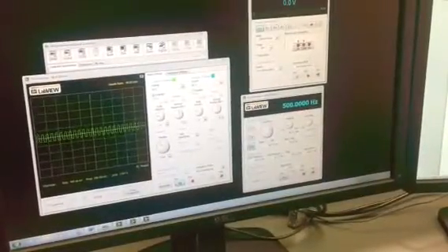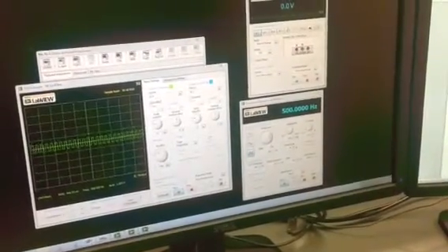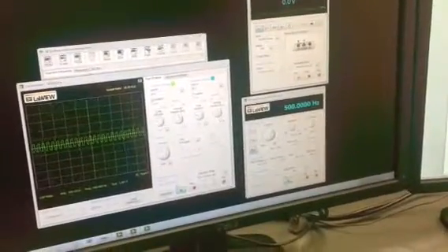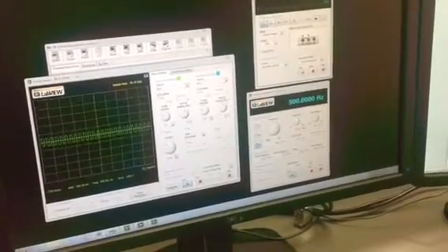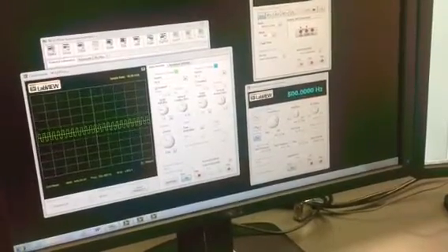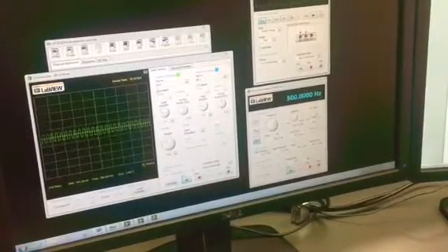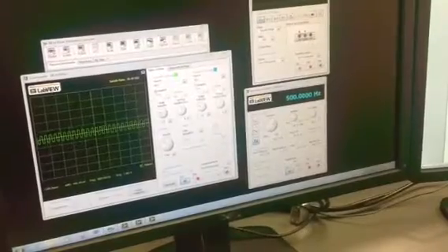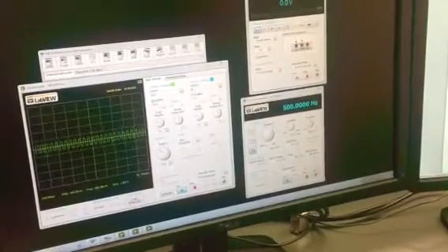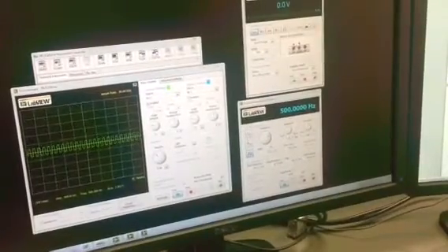For part 8, use a square wave of amplitude 2 volts peak-to-peak as the input voltage into the RC circuit. With the myDAQ set up to read the RMS voltage across the resistor, write down the RMS voltage for each of the following functions and try to get the oscilloscope to look like the corresponding figure. Also, for each function, set up the myDAQ to read the RMS voltage across the capacitor using part 7, which is basically what we just did there. For each function, write down the RMS voltage of both the resistor and capacitor and draw a rough sketch of the oscilloscope for the myDAQ setup to read the voltage across the capacitor.